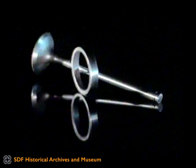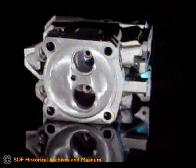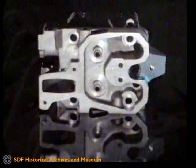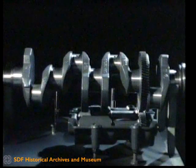Finally, the top sealing ring cavity on the turbocharged 1000 series engine is made with a high temperature resistant cast iron ring holder, so as to avoid wear of the actual cavity. Valve seat inserts, made of molybdenum, chrome and vanadium cast iron with a low carbon content, in order for it to have a toughness close to that of steel and a high wear resistance, particularly at low temperature. Better long-term tightness. Engine shafts with discharge grooves.